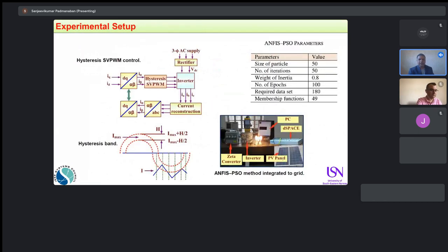This is an experimental setup where we try to incorporate photovoltaic systems, particularly focused on photovoltaics. So photovoltaic systems are connected to the zeta converters and inverters. So the zeta converter is a DC converter to increase the power, and the inverters are connected to the grid. And we used a large nonlinear load as a lamp system to create a huge lagging power factor load, reactive loads.